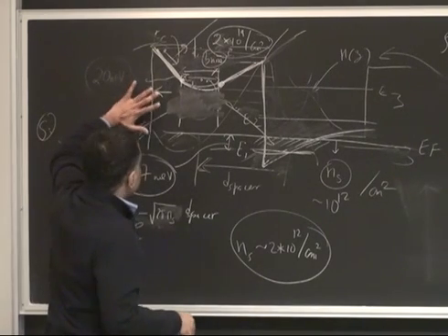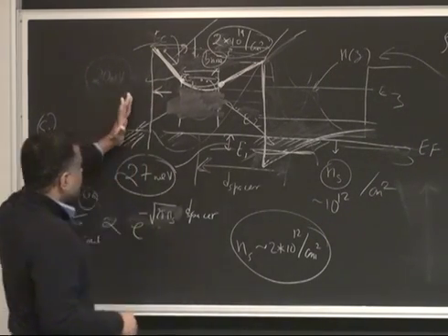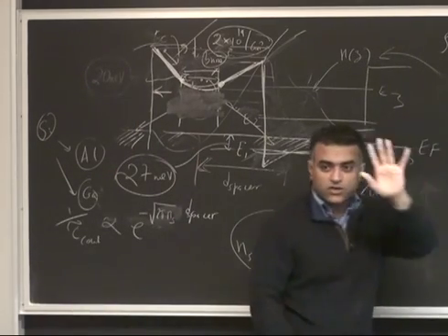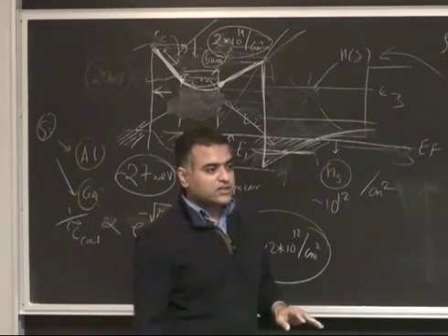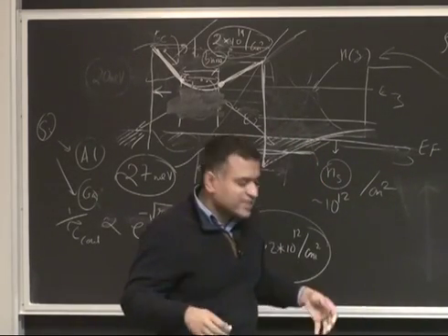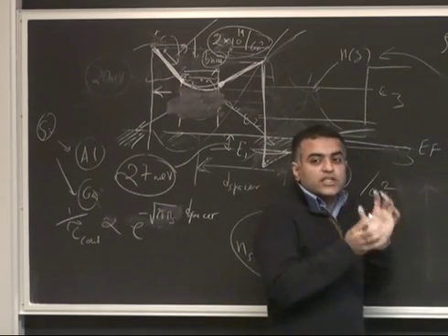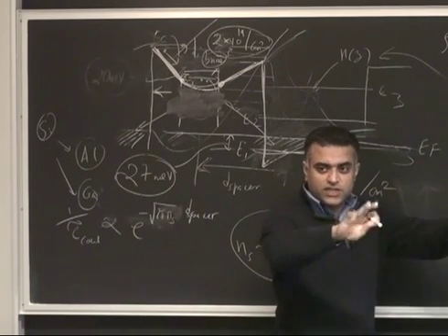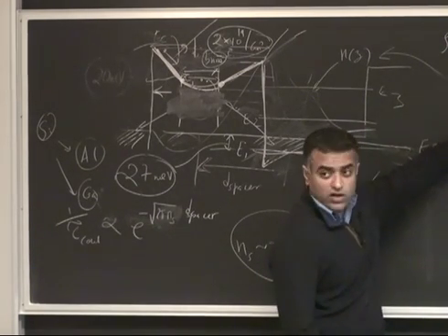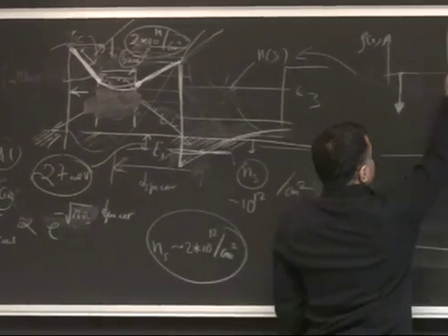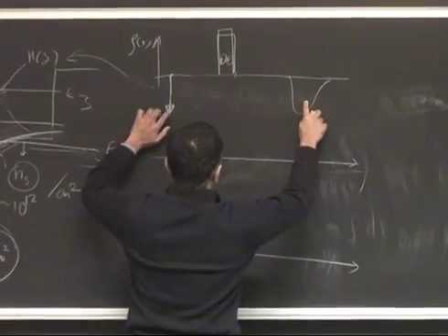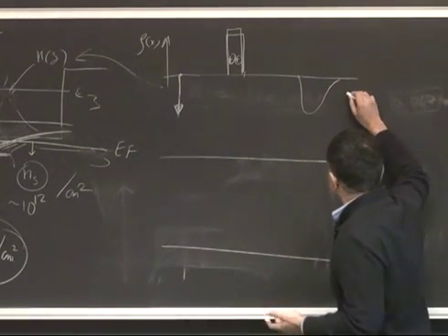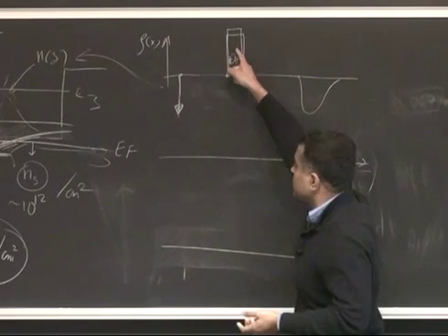So you have a charge on the metal, but I think we all know that the charge in a metal cannot be spread out. It's always a sheet charge, always on the surface of the metal. This is from electrostatics. Because the conductivity of a metal is effectively infinite, it cannot support electric field inside, so there cannot be distributed charge inside a metal. It's always pushed to the surface. So the electrons in the metal are all on the surface as a sheet charge. Here's your dopant charge, and here's the mobile 2D electron gas, and they must all sum up to zero. And what we found, for example, here, is 2e12, 8e12, and 1e13.